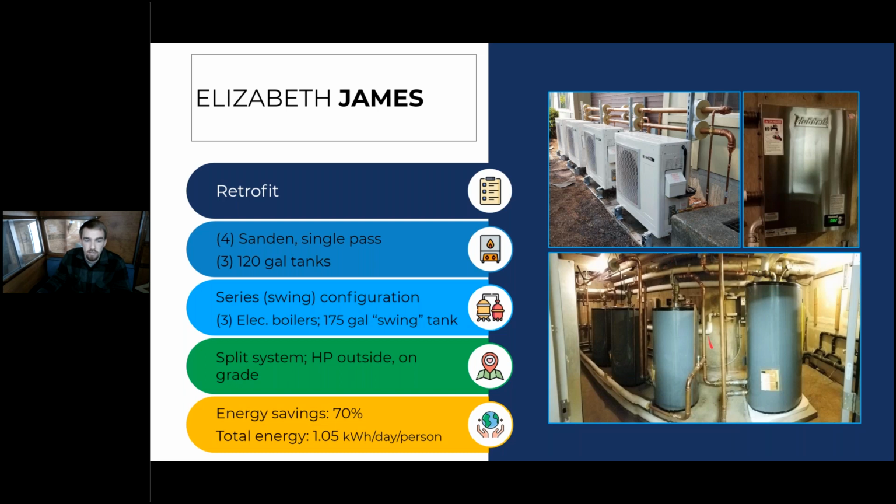So this hot water is flowing through this final tank that's also receiving circulated return water. So the overall temperature of this tank is maintained above what we need to serve to the building. So it's always warm enough. And then we have these 3 electric resistance water heaters that were original equipment in the building, but they're now being used as redundant heating as well as temperature maintenance heaters for those times of low usage when we don't have the hot flow from this primary storage warming up this temperature maintenance tank.